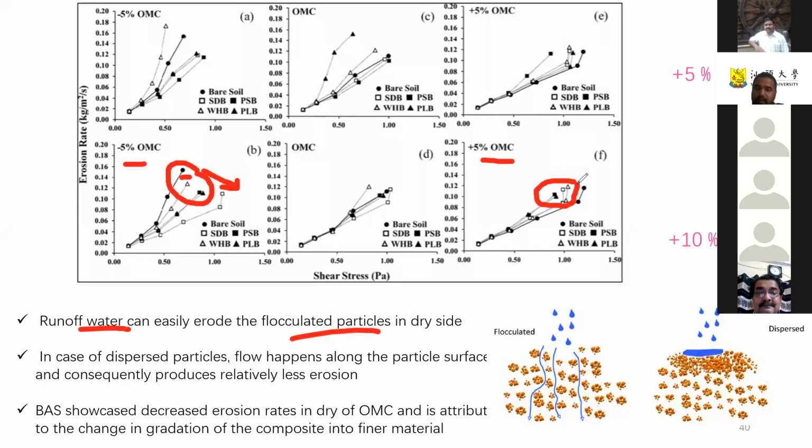So it means when your soil is very dry and the rainfall comes, in the subsurface flow, there is a tendency that biochar can prevent or minimize the erosion rate. But if the soil is saturated or nearly saturated, and a rainfall comes with very high subsurface flow, the effect of biochar becomes very negligible. One reason is the hydrophobic groups of biochar, which become quite active in repelling water, and this washing away of biochar happens.